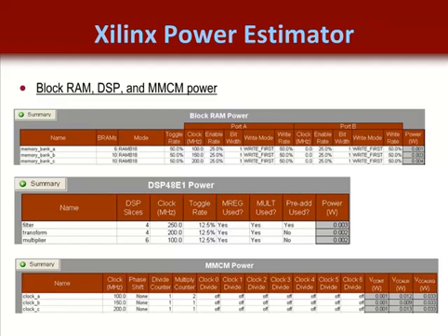This slide shows you how your block RAM, DSP slice, and your clock management resources, that is the MMCM resources, can be customized for the power estimator. The block RAM and DSP slice resources need a little more information that is specific to those resources than, say, the CLB resources needed. The clock manager, or MMCMs, need specific information about how each derived clock signal is going to be made. You may recall that each has the ability to derive up to 6 clocks and will be dependent on how each clock output was derived and its frequency.